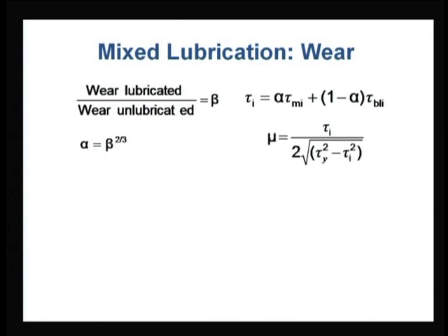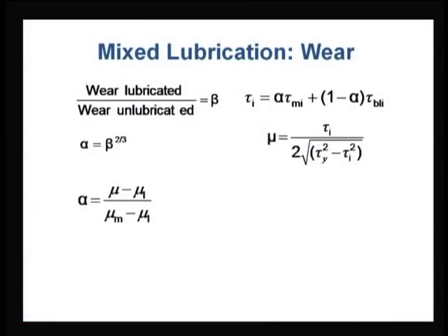Instead of going with extensive experiments based on superimposition of individual wear mechanisms, this requires a much smaller number of experiments and then gives some sort of conclusion which is reliable for most materials. There is another possibility: if we do extensive experiments in the presence of the lubrication mechanism and in its absence, alpha can be figured out using this relation also.